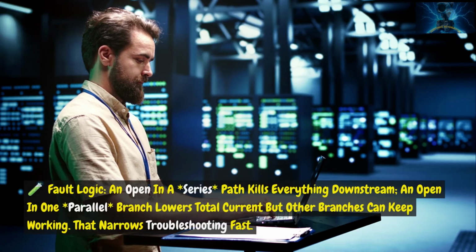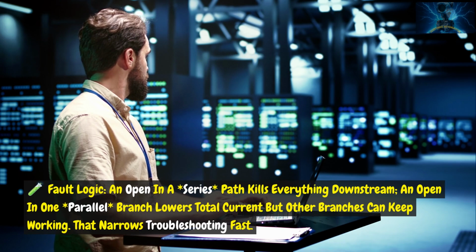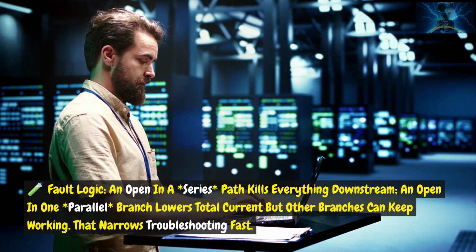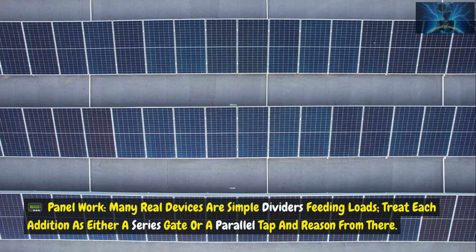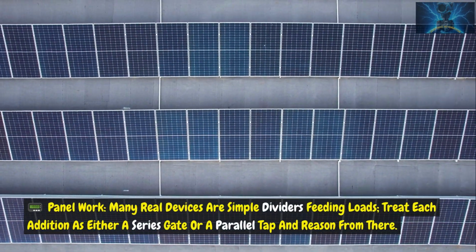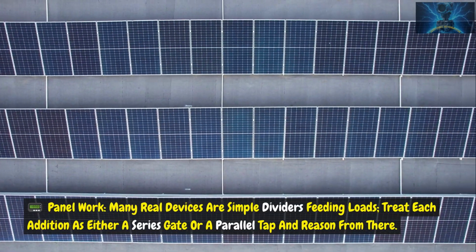Fault logic. An open in a series path kills everything downstream. An open in one parallel branch lowers total current, but other branches can keep working. That narrows troubleshooting fast. Panel work. Many real devices are simple dividers feeding loads. Treat each addition as either a series gate or a parallel tap and reason from there.